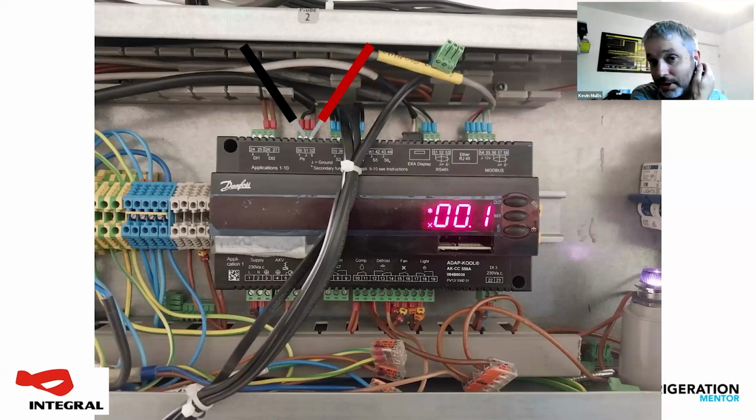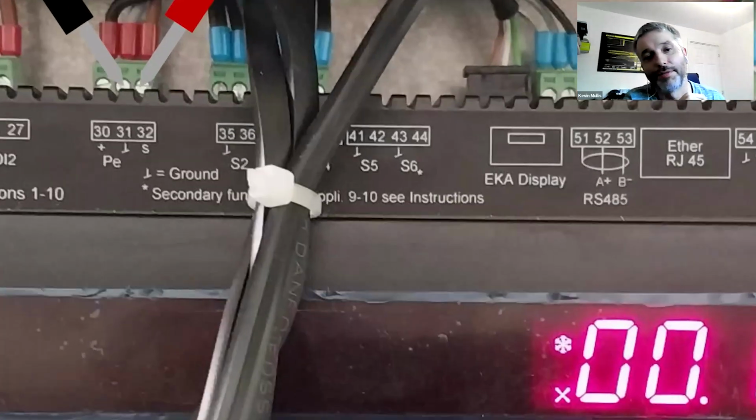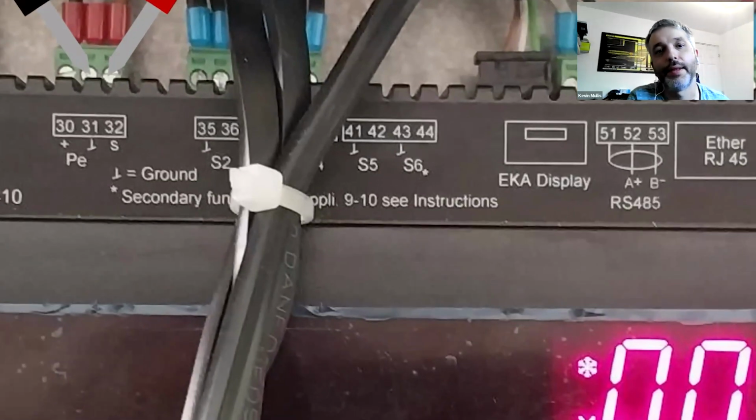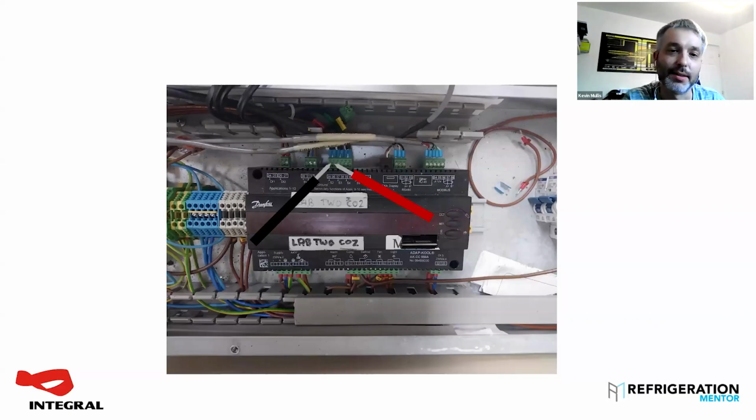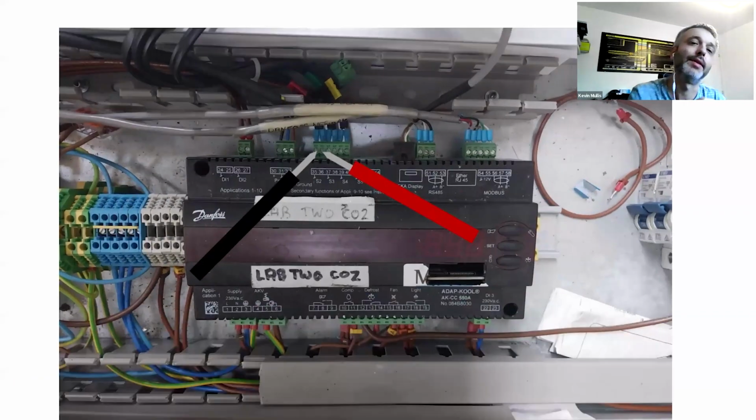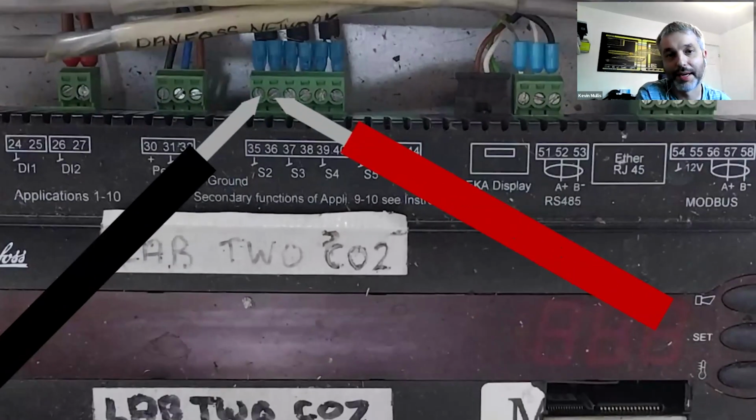And actually, up on the top plugs, you can unplug the defrost sensor. If there's S5 in there, it's probably S5. If it's air off, it'll be S4. And you can do a resistance check on your probe. The Danfoss likes PT1000 probes.